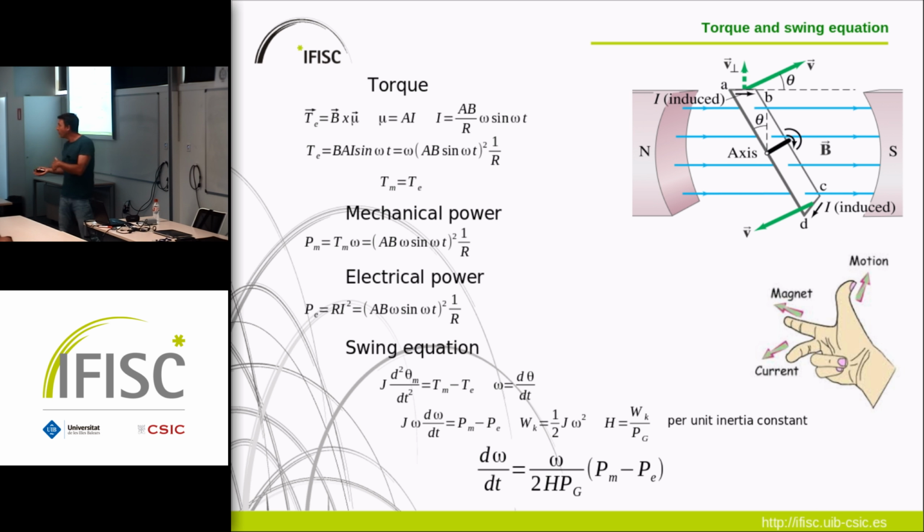So I'm more concerned about the torque. So what happens here is that, as I said, you have a magnetic field and you have a coil rotating. You remember this from your basic physics course, no? So you have a magnetic field and you have a current in this magnetic field. You have a force acting on the current, okay, that goes upward. So if you have here a magnetic dipole, essentially, in a magnetic field you get a torque.